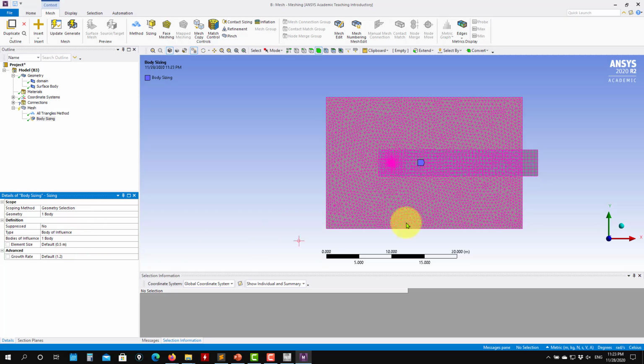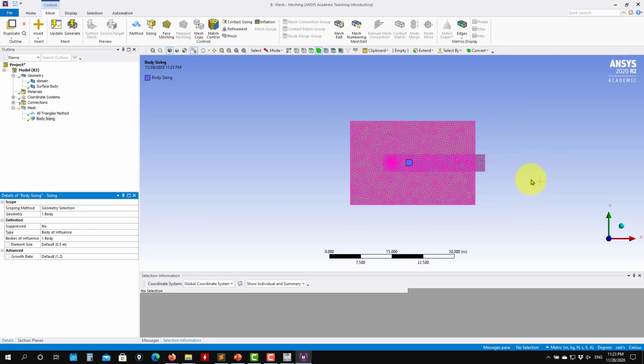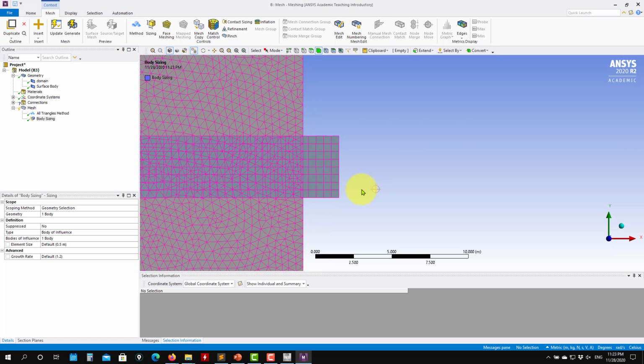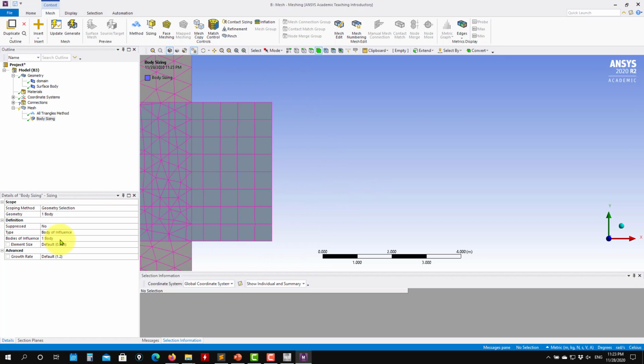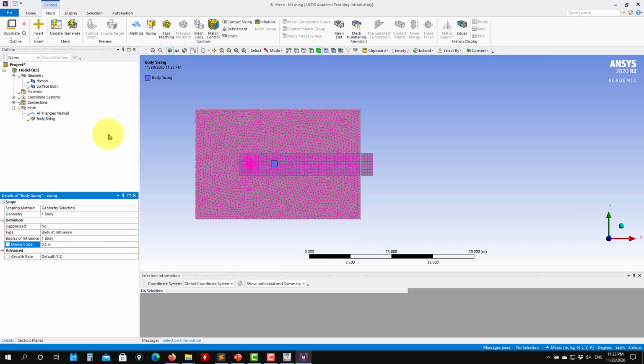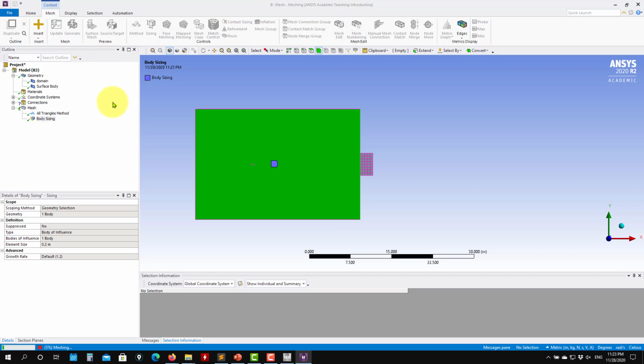Okay, and inside this geometry, I want this dimension. So if I zoom in again, see the circle, it will give you a reference. If I put here 0.1, see that the elements there will be about that size. So let me put 0.2. Okay, as you press generate,